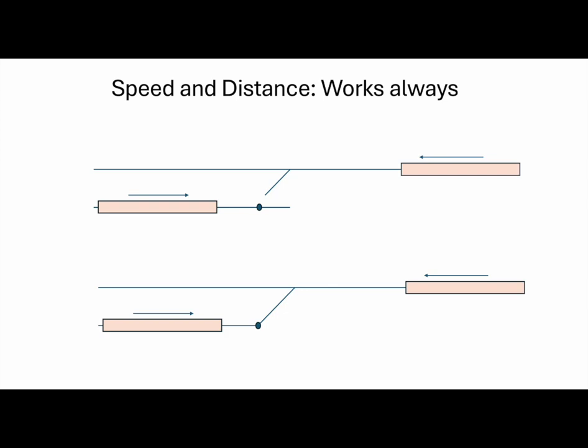Now the TMS, of course, has to think about it, because creating situations like that allows higher speeds, so it can optimize, but it also moves more points. Depending on the distances, it can optimize what it wants to do. If the distance is high, so the other train is far away, you can avoid moving points for flank protection, but if they are near, it needs to do it. So the TMS now has the option to optimize in terms of capacity, asset usage, and configuration of the status. But the train-centric rule is very trivial and basic and always works.